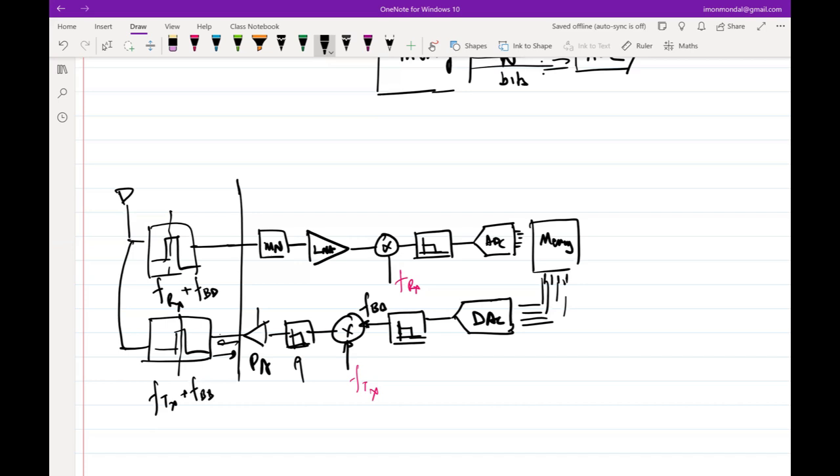The only reason they come up is that we need to ensure PAs operate at very high efficiency, and efficiency and matching sometimes trade off against each other. Okay. So the reflection is in such a way that the output voltage is increasing. Yes. You can as well reduce the gain of the PA. That we don't want to do. Well, again, it's a design trade-off, right?